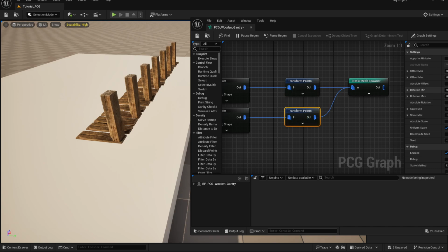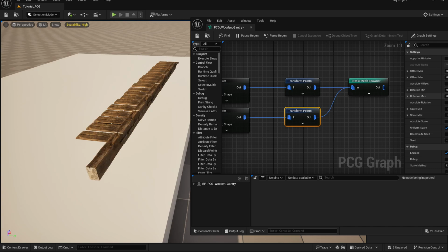This time we're going to rotate it on the Y. And if I rotate it 90-90, you'll notice it's not really rotating in the correct direction. So what we really need to do is rotate it by minus 90 degrees to minus 90 degrees. And I'm not going to mess around with adding any wiggle room there. I'm not going to do minus 89 to minus 91. I want it to be flat minus 90 for the stability that it's going to offer there.